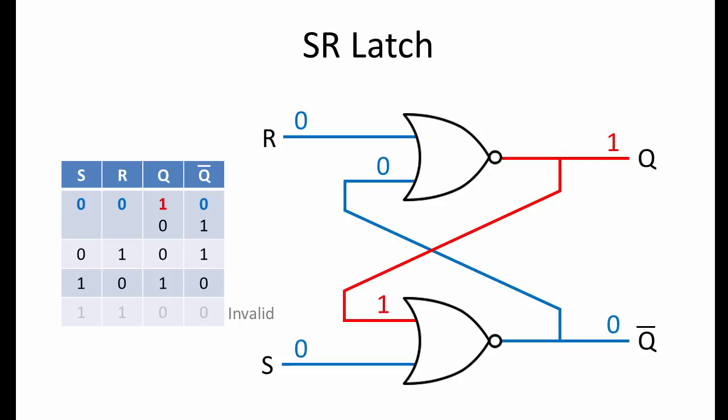And at any time while it's operating, the SR latch should either be in a set state or a reset state, with Q and not Q the opposite of each other. One final piece of terminology. This type of SR latch is said to be an active high SR latch, because the normal condition for S and R is low, and a high pulse at one of these inputs is required to bring about a change.